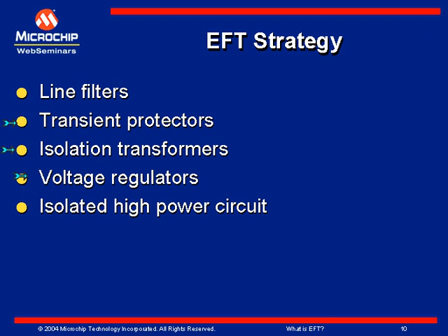In that case, you may not have voltage regulators or isolation transformers, so whatever noise is there on the power lines directly comes into the system. One more fix for this is to use isolated high power circuitry. If you use opto isolation between your low level digital logic circuitry and high power circuitry, that again helps, because digital circuitry or sensitive components are not seeing those high frequency power circuitry directly.